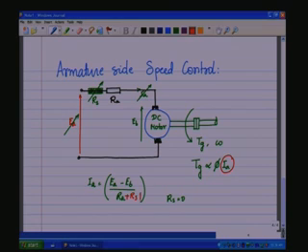We are increasing RS. The moment RS is increased, IA is going to reduce. Reduction in IA is going to result in reduction in the generated torque TG, which is going to reduce the speed omega for the same load, and that is going to reduce the back EMF EB, and that will settle at a new operating point.